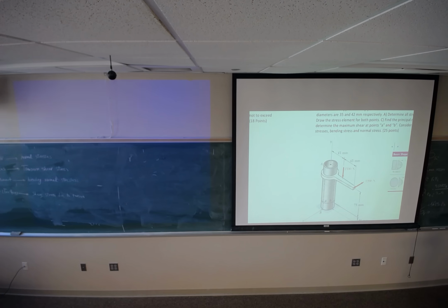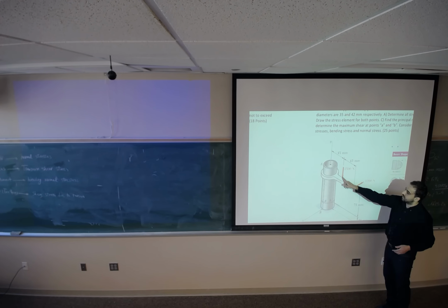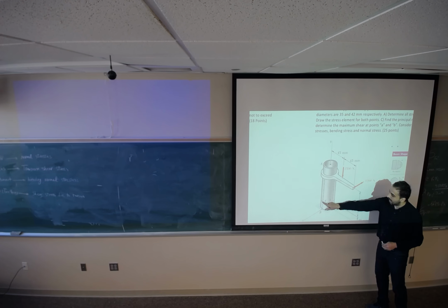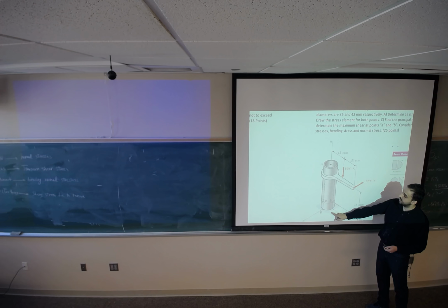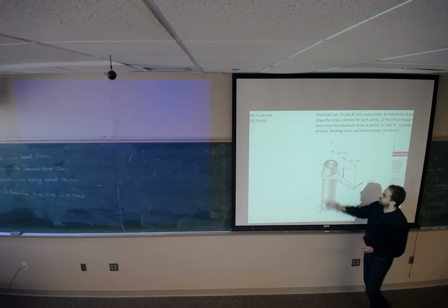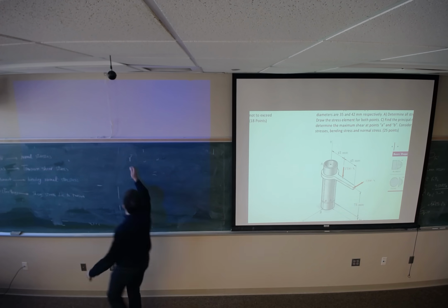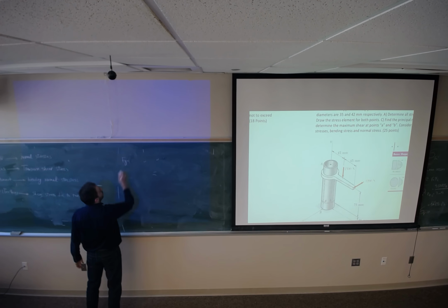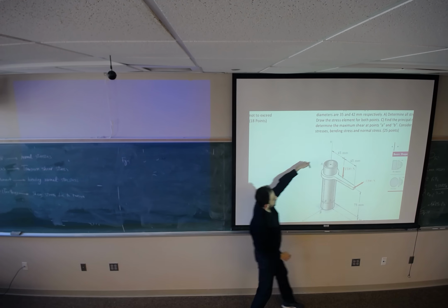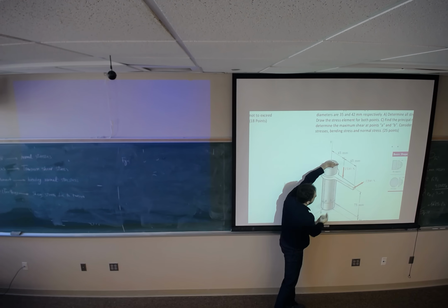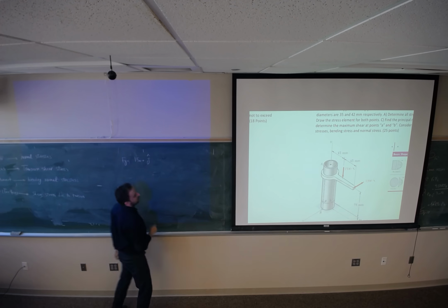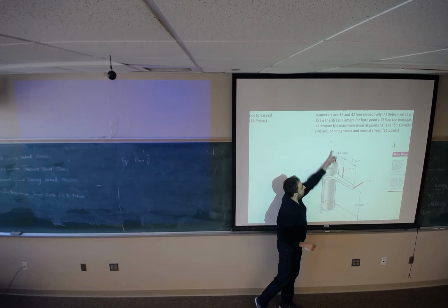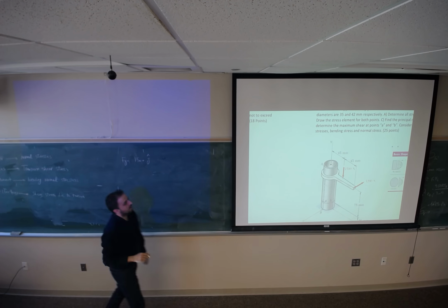So let me start with this force. This force at this section is making a reaction in the axial direction, which is y. In the opposite direction, I say F_y equals 1500 downward. Here it should apply upward. The direction is j. Y-axis means going up, so j.